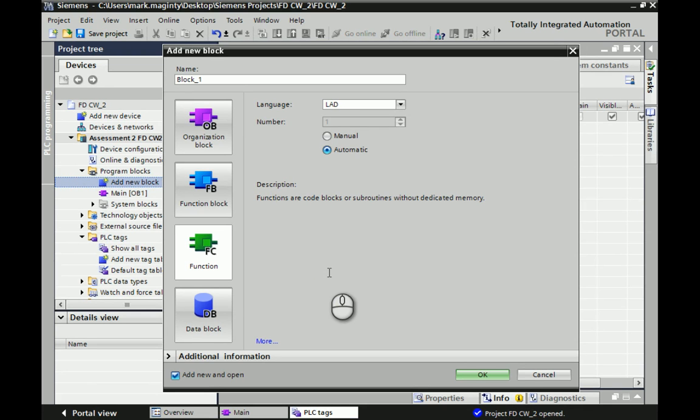Okay, so those are the two that the inputs and outputs need to be at a low enough value, as in around I0.0, through to I think a maximum for the 1214C is I think 10 inputs worth and about 12 outputs worth, somewhere in around there. So we need to make sure that we can fit all the I/O for the traffic lights and the car park within that stretch of I/O.